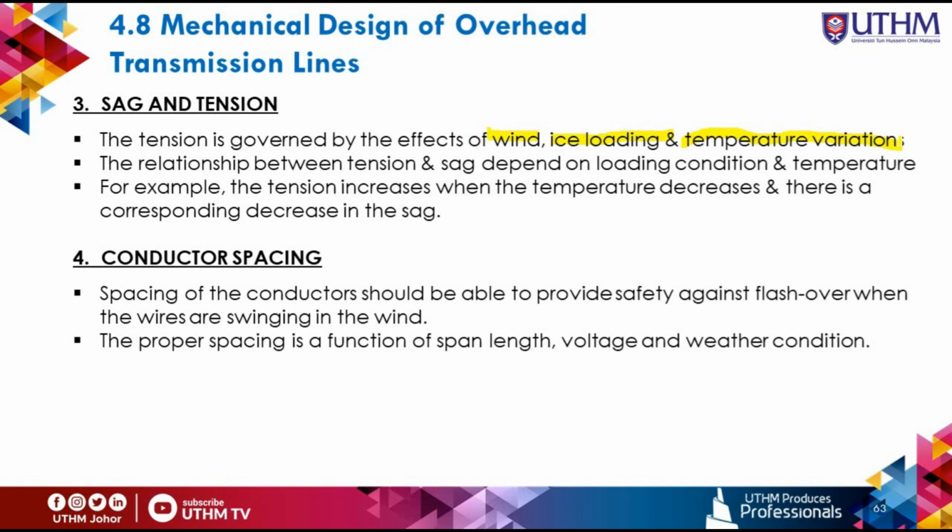So the relationship between tension and sag depends on the loading condition and also the temperature variation. For example, the tension increases when the temperature decreases and there is a corresponding decrease in the sag.